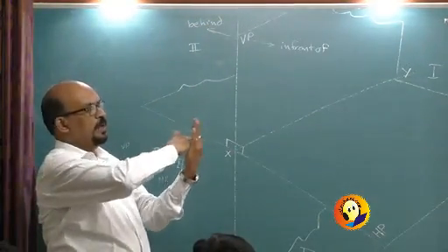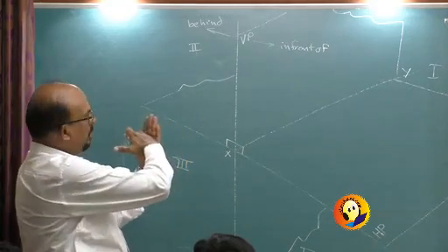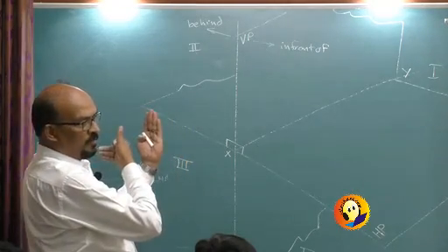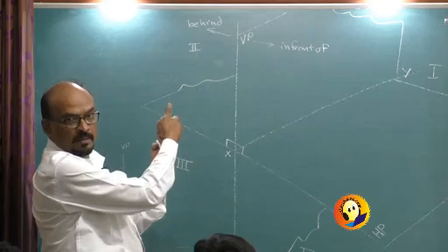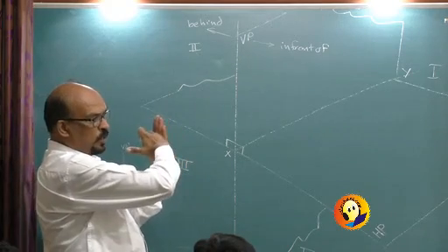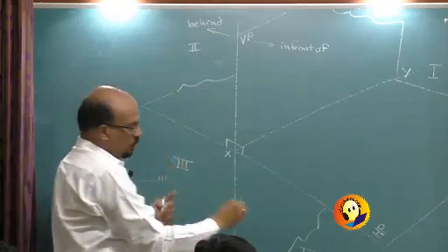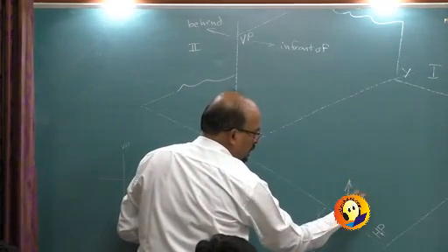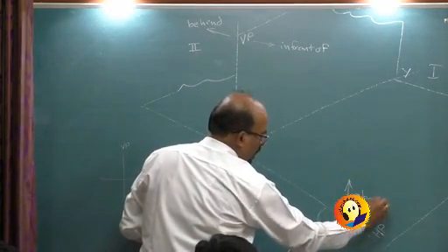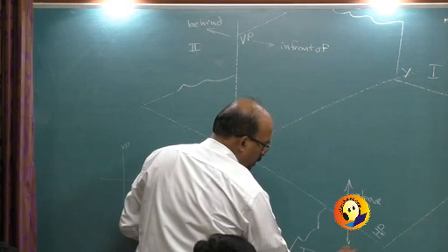So this is how we look at it. This is horizontal plane, vertical plane, it is in front of VP or behind VP. Now with reference to horizontal plane, it will be above HP or below HP. So this portion is above HP and this is below HP.